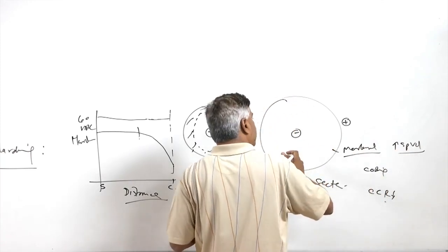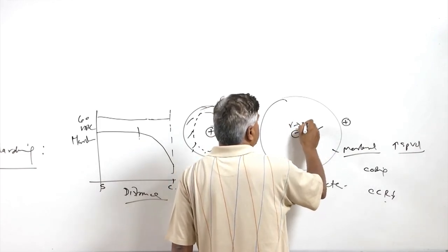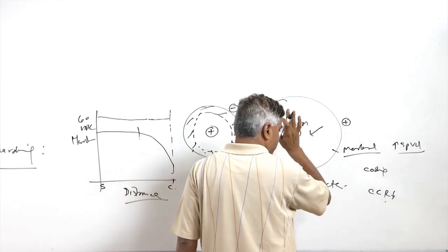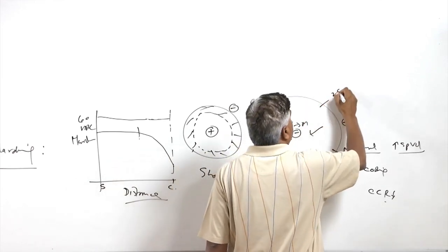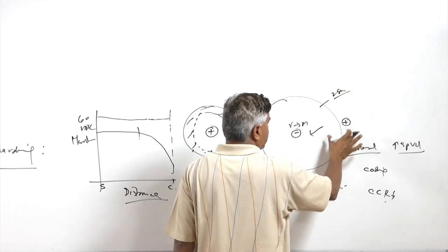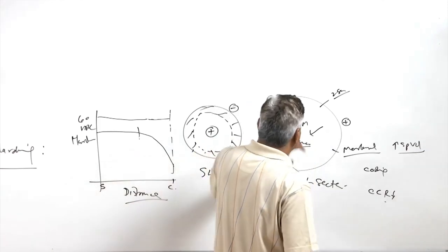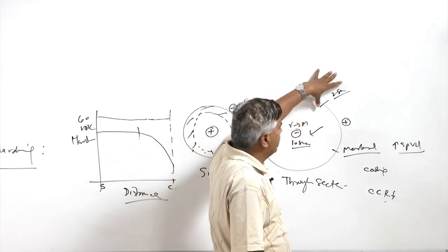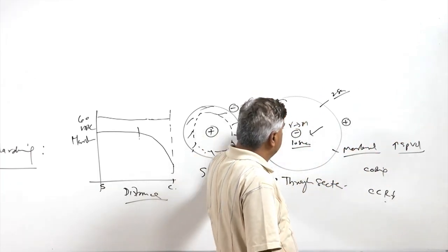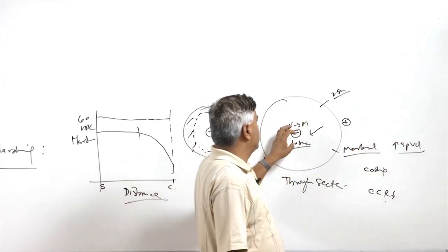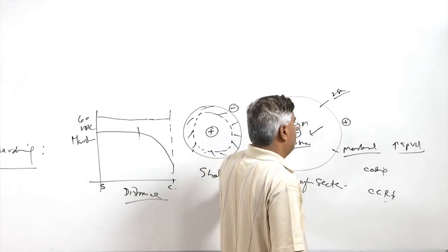the austenite to martensite transformation at the center occurs subsequently. Say in quenching, just within 2 seconds the transformation occurs at the surface, and after 10 seconds the transformation occurs at the middle. So the first transformation occurs at the surface, forming the martensite, which is very hard and brittle, and subsequently the transformation occurs at the center with an increase of specific volume, forming hard and brittle martensite.